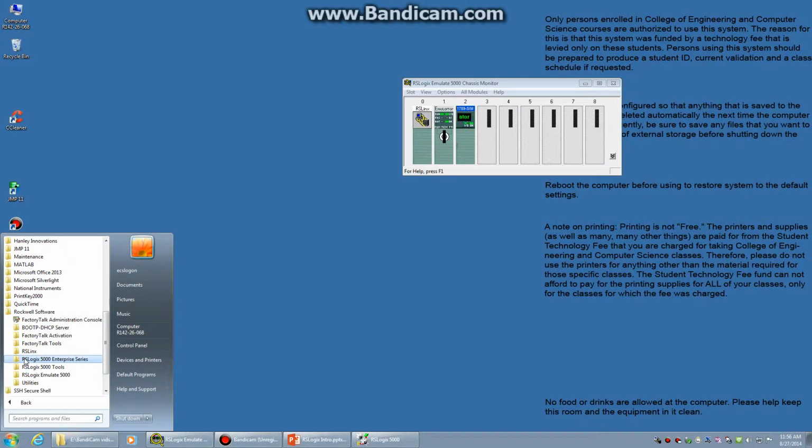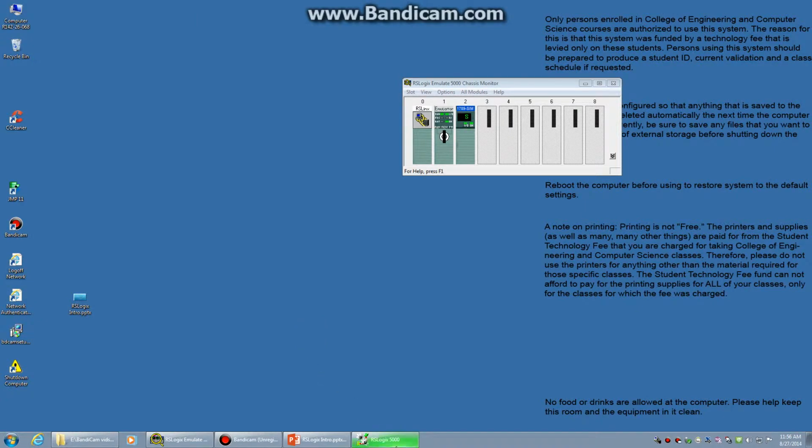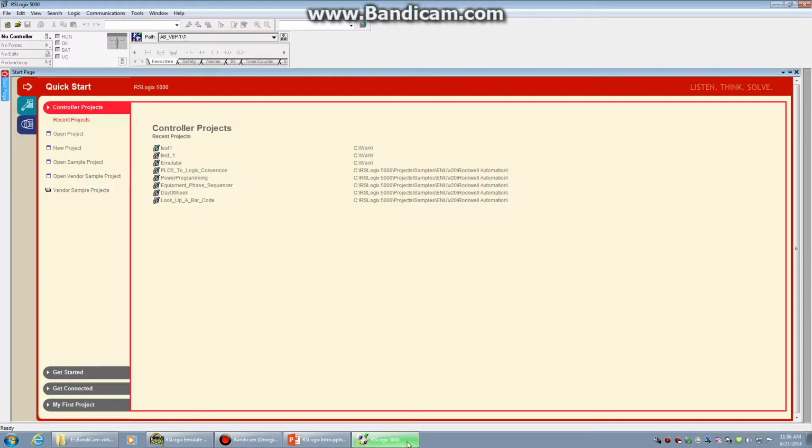The other software we use in lab is going to be RSLogix Emulate 5000. Now an emulator helps simulate a PLC so that we can test our software without actually connecting it to the hardware. This you will find is very handy. Now I've preloaded it because it does actually take a couple minutes to load up the software, and I don't have that much time in these videos.